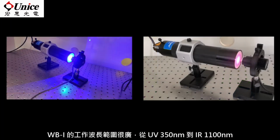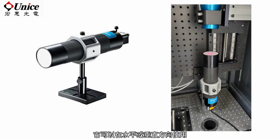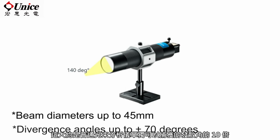The WBI operates over a wide range of wavelengths from the UV 350 nanometers to the near IR 1100 nanometers for powers from hundreds of microwatts up to 1 kilowatt CW. It can be used in a horizontal or vertical orientation, with beams having diameters up to 45 millimeters and divergence angles up to plus minus 70 degrees. That's roughly 10 times the divergence angle that can be captured by a regular profiler camera alone.